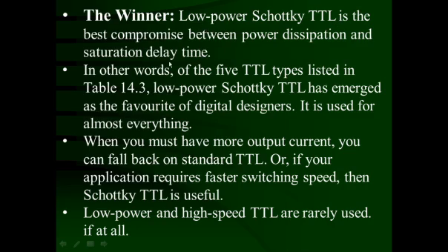Low power Schottky TTL is the best compromise between power dissipation and saturation delay time. In other words, of the 5 types of TTLs listed in table 4.3, low power Schottky TTL has emerged as the favorite of digital designers. It is used for almost everything. When you must have more output current, you can fall back to the standard TTL.